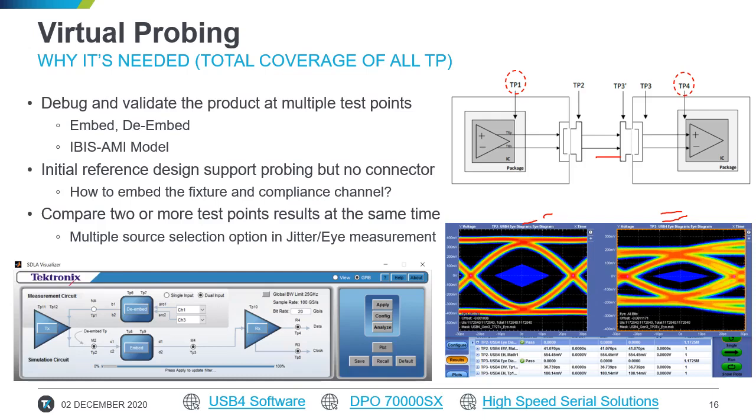Another important aspect of virtual probing is using the IBIS-AMI model in the receiver equalization. That means using the CTLE and DFE adaptation as implemented in the receiver and seeing how those jitter numbers look and what the best CTLE coming out is. It's always about how it is equalizing: is it over equalizing, under equalizing, or optimally equalizing?